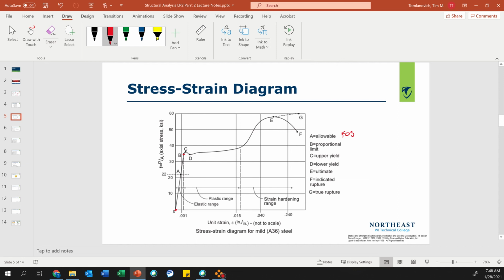So if we remember what stress is, it equals force divided by area. That load was that tower, okay? What happens to stress when the area gets smaller? When I do math, when area goes down, the stress goes up, and then what happened was it exceeded the allowable stress. It deformed. Okay, so that's what happened in the Leo Frigo Bridge.